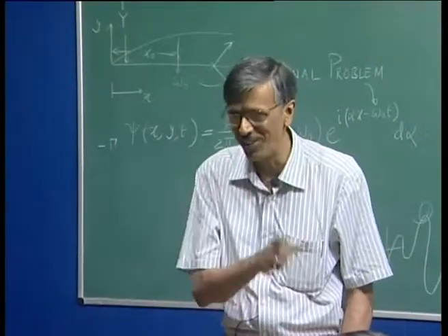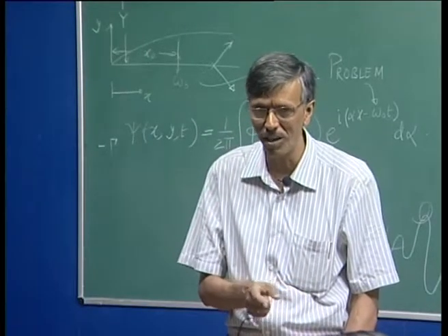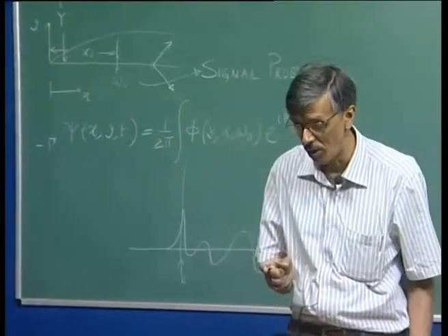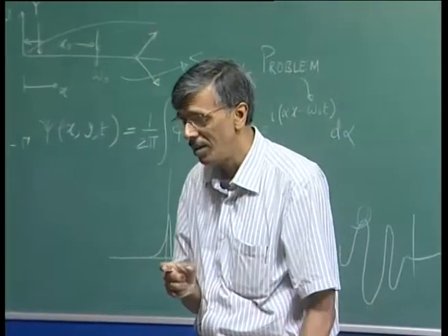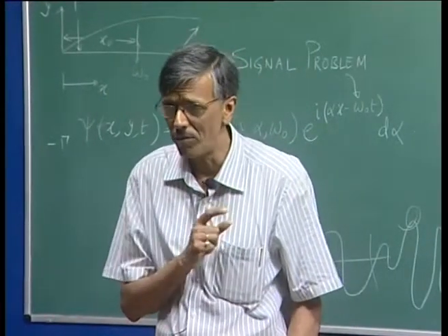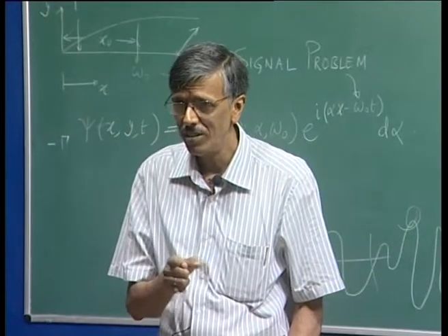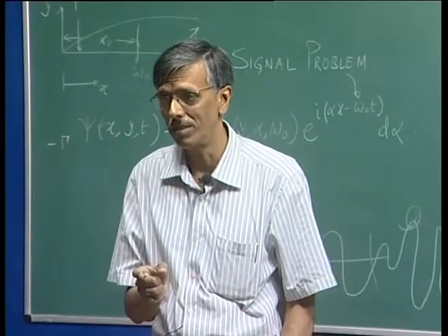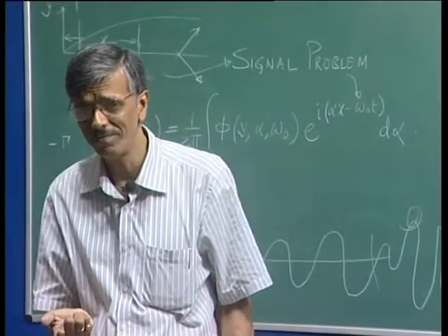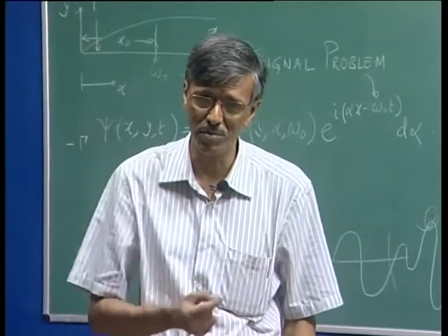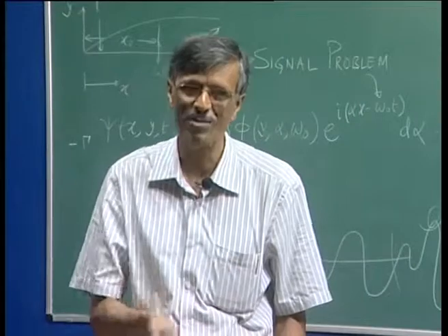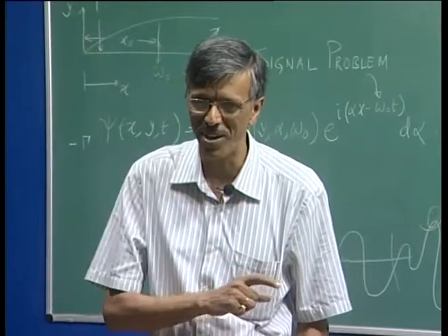To do that, we have to again recompute the group velocity and make sure that they are indeed going upstream or downstream. And you also have to be very, very careful now in talking about the value of alpha I for which you will have stability or you will have instability. Why? Simply this: if you are looking at the upstream propagating wave, alpha I should be what? If it is to grow, alpha I should be positive. So, this is just a complementary picture.